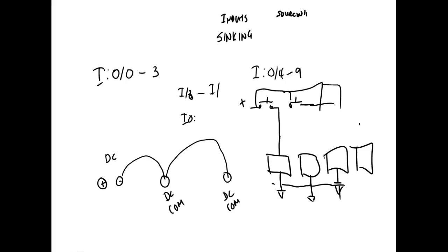Now, on a modular PLC, you buy the power module. Is it obvious to sync? Yeah, we went down there. If you look at the SLC 504s, if you look at the input module, it says syncing. If you look at the output module, it's written on the module, it says what? Source. So you don't hook the power supply up to those guys. They get it through the bus that runs down the backplane. So your DC power supply runs down the backplane.